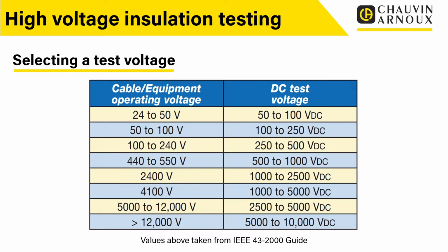So depending on the application that you're working on, depending on the actual type of equipment and its rating, that's what we would look at to see what would be a suitable test voltage. So this was taken from an IEEE guide. But again, this is quite common in many standards, and it's always worth looking if you've got equipment that's rated to, or certified to, a certain standard. Obviously, have a look in that standard to see what test voltage they recommend, and we'd also recommend consulting the manufacturer.